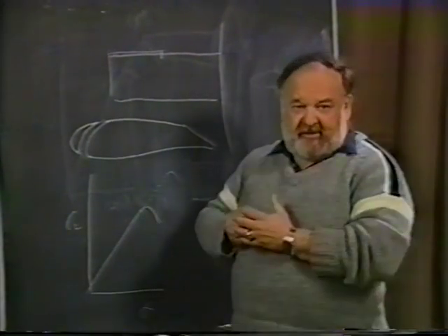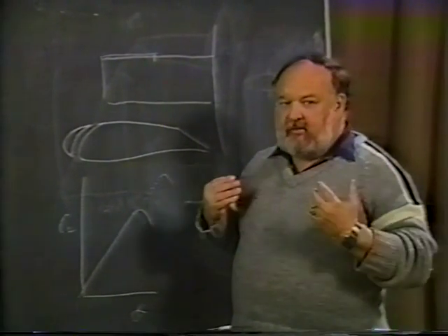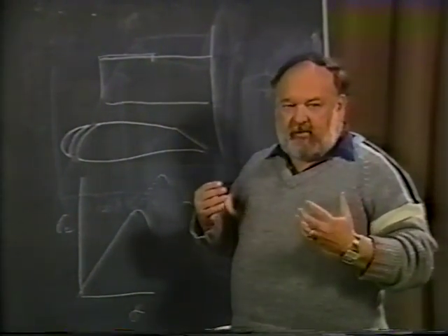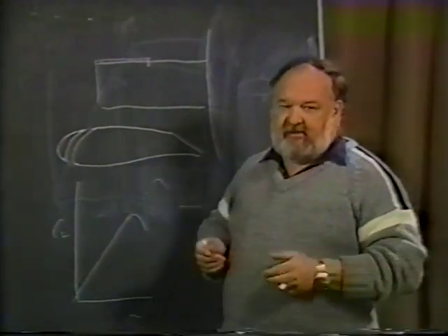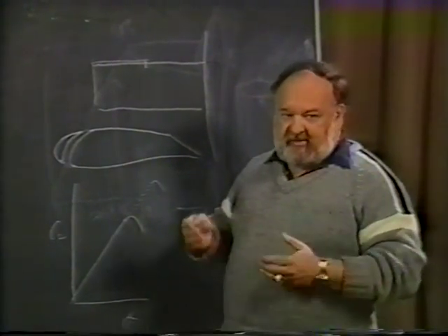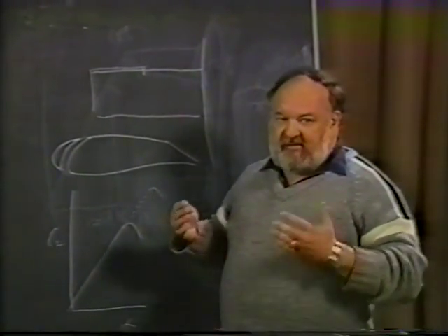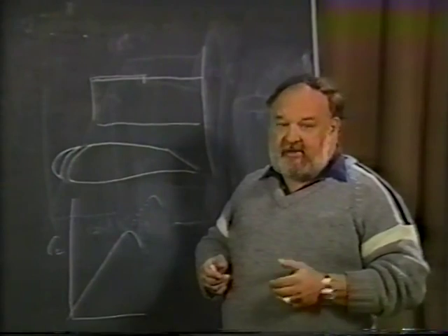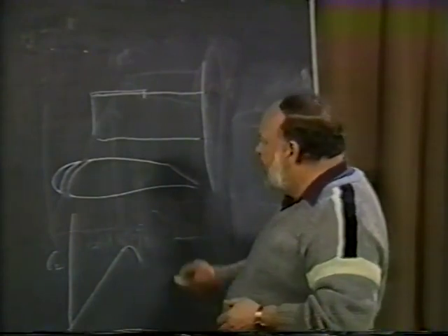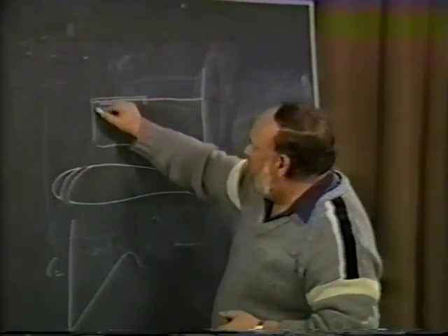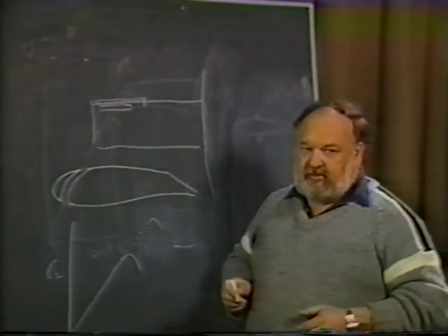If it's a type like a movable slot that rolls in and out, then you have a nice advantage in the fact that when it's closed, you do not have any more drag than the standard airfoil would have. When it's open and at high angles of attack, you now have the high lift characteristics. The disadvantage, of course, is that you have to make more parts, more mechanism, and design it just properly. But when you look at any of the jet airliners, they all have some form of leading edge treatment because it's an important thing. It can and will enhance the lifting capabilities of the wing quite a bit. But a fixed slot or a movable slot out here in the outboard section will give you that stall pattern and that spin characteristic that you're looking for. It will do a good job.